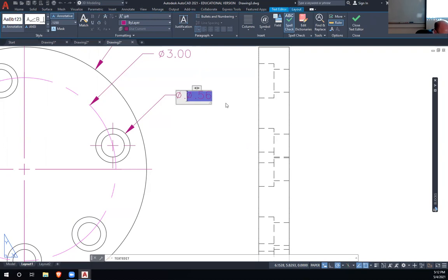And there's my 0.375 for my 3/8. I'll hit enter and that puts that in there. And that's actually the dimension of the outer hole, which is the counterbore. So I need a lowercase v, which is the whole reason we use that GDT font: the lowercase letters are symbols, and the counterbore is one of them. A countersink is W, right? And that's the angled counterbore, basically.